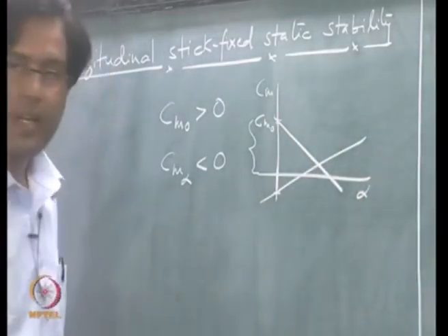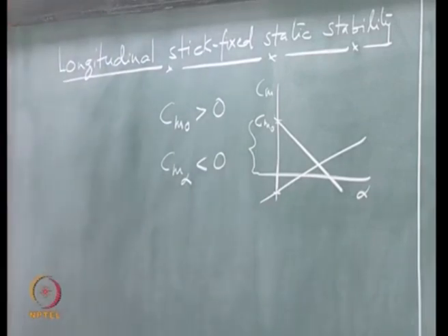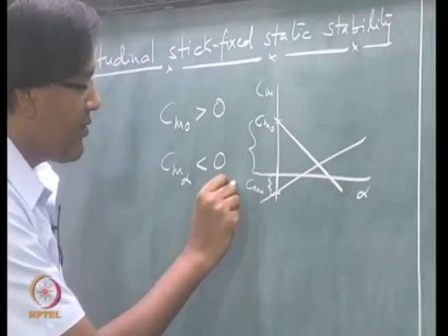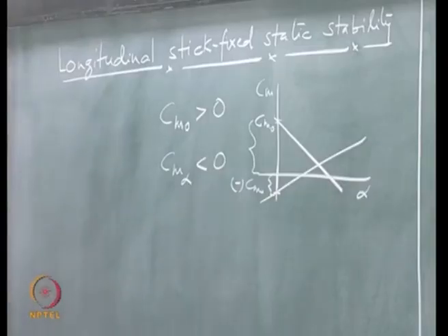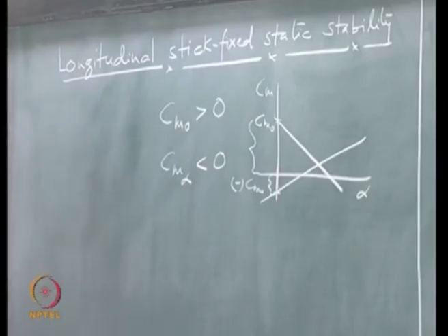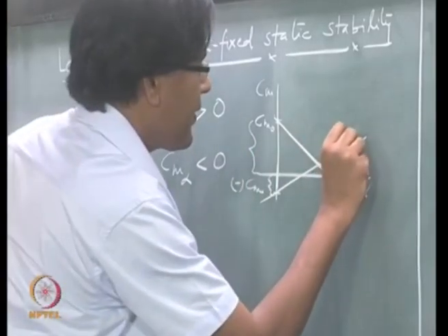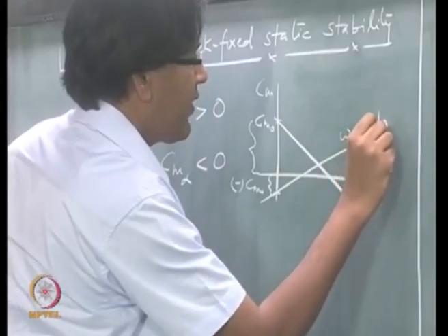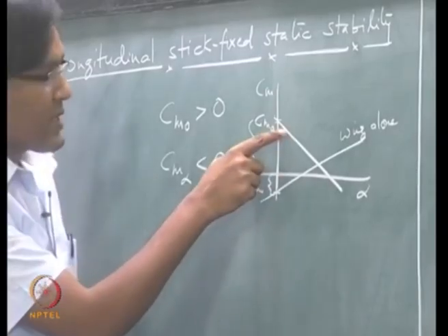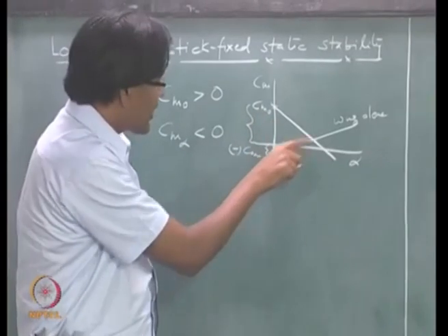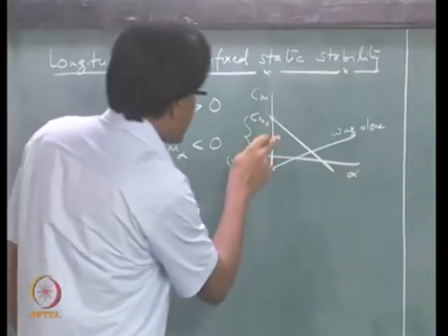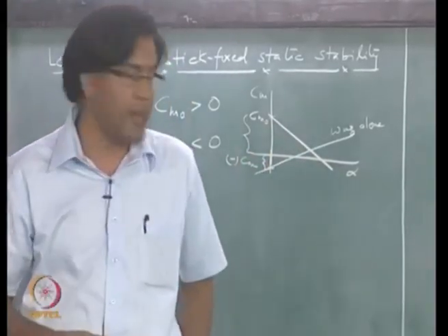So, for positive cambered airfoil, the wing gives you this Cm naught, which is negative, and Cm alpha is having a positive slope, right. And this is what is desired, right. This is what you get from the wing alone contribution, and this is what is desired for the airplane.